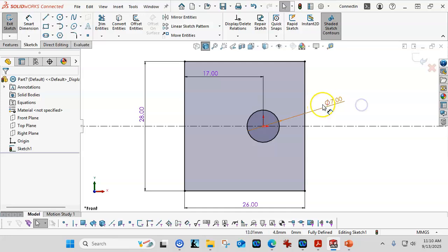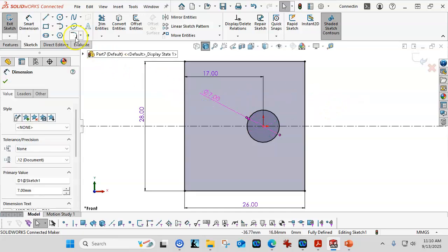Okay, so the arc, let's get that out of the way. We've done center point arc, tangent arc, not really the 3-point arc. This is a good spot to do the 3-point arc because I really don't know where the center is. Radius of 12 isn't that big, but it does give us the option to also use the symmetric relation.